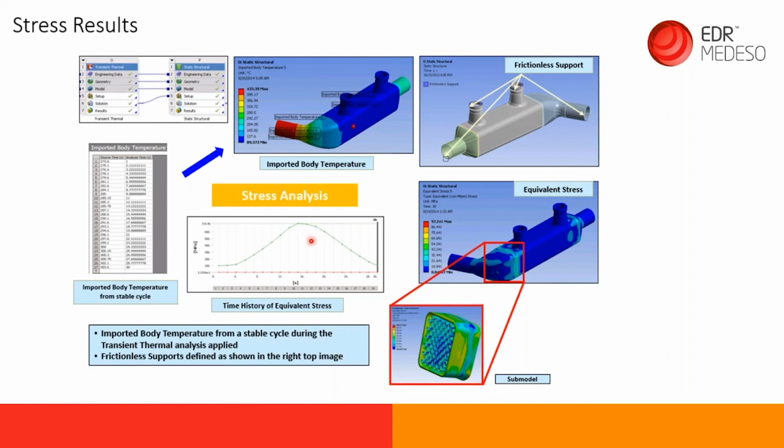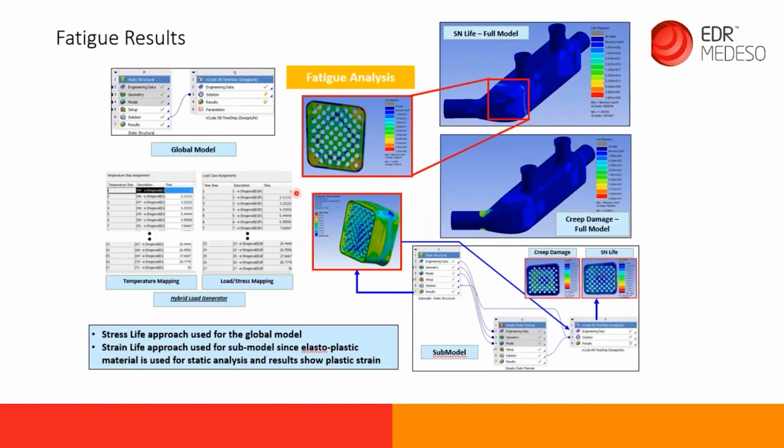We can then pass that on to a fatigue analysis using another simulation. What the fatigue analysis does is it essentially tells us how long this component is going to last, where it's going to fail and how, and we can use that whole process as a design loop to go back and make sure this kind of thing doesn't happen.